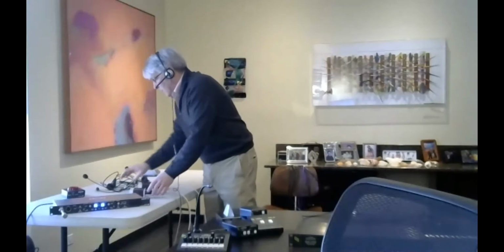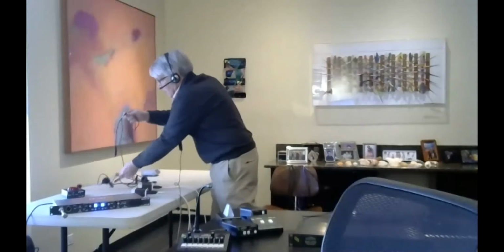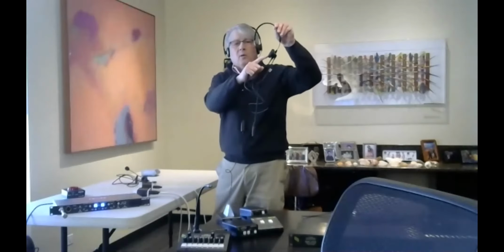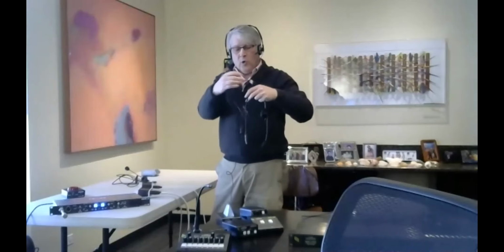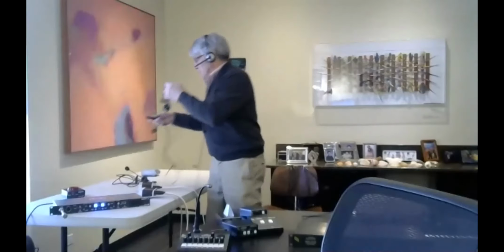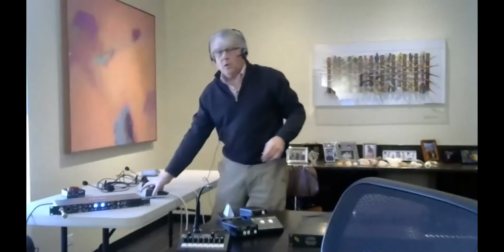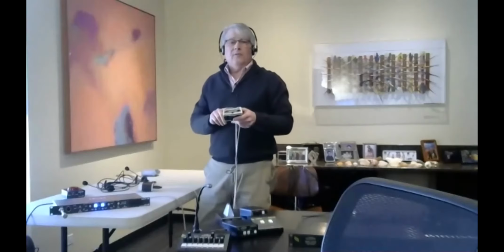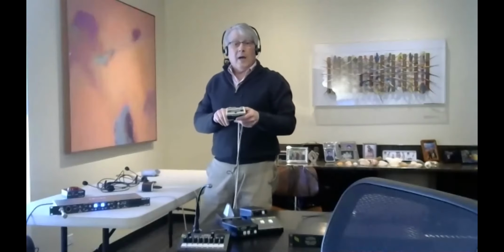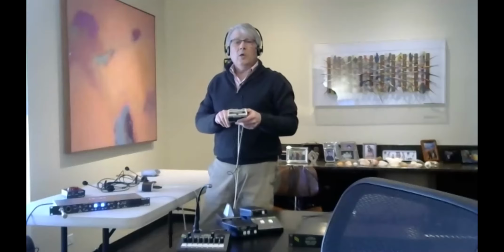Obviously, you need something for the user to use. And I've got here a single earpiece, single muff, uses a 4-pin female XLR. I plug it into the belt pack and away I go. So over a single XLR, you have pin 1 common, you have power on pin 2, and then you have audio for everybody, talk and listen on pin 3.